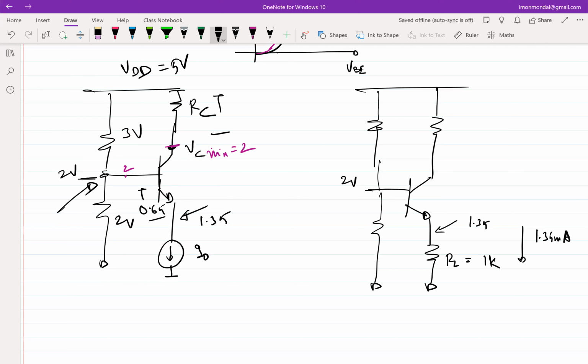Okay. Any questions? Pardon? Yeah. So this is something that you will do in your labs also, in 380 labs, right? Especially on boards, it's not very trivial to get current sources. So a replacement of a current source is essentially a large resistor, and whatever is large is dependent on the context of whatever it is connected to, right?